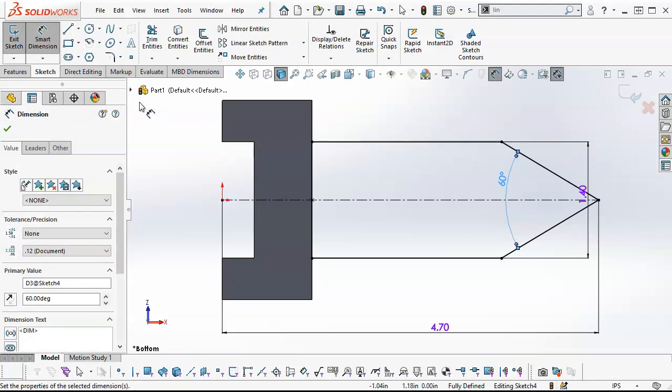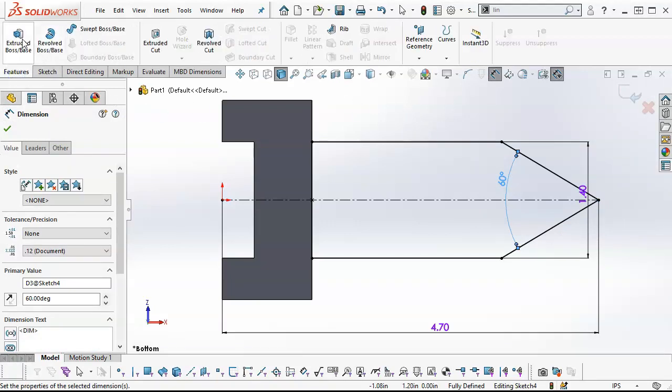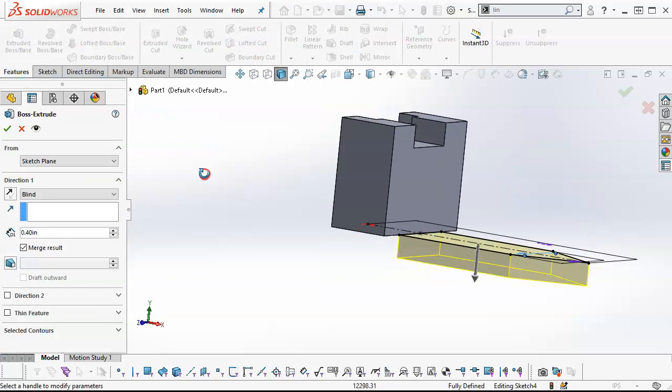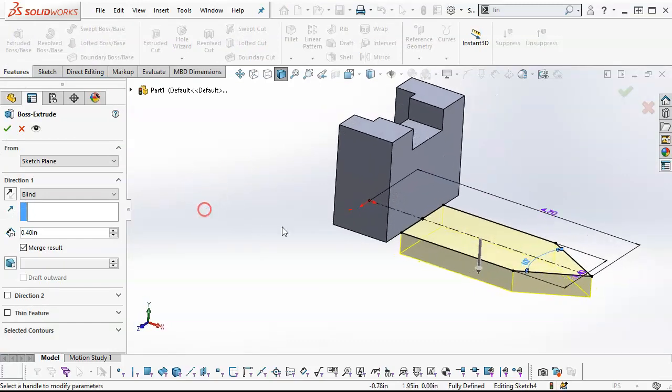And then when I go into the feature and tell it to extrude, it's showing me the direction that it's selected, which is away. And this would, in previous versions, okay, way back in the early 2000s, have created a disjointed figure. Now it would just create 2 solid bodies. Right, so we'd have solid body on the left, solid body on the right, because they're sharing an edge and there is no overlap of geometry. So I can reverse it.